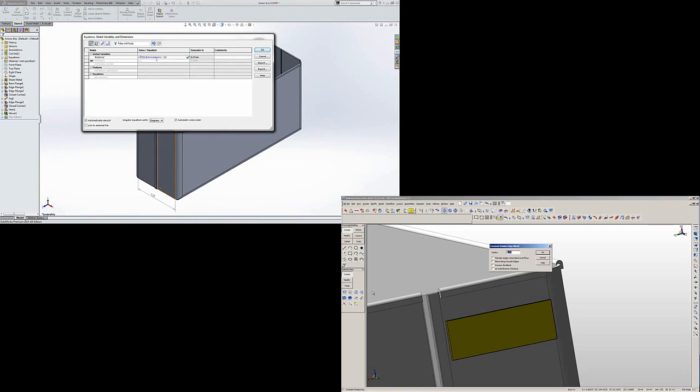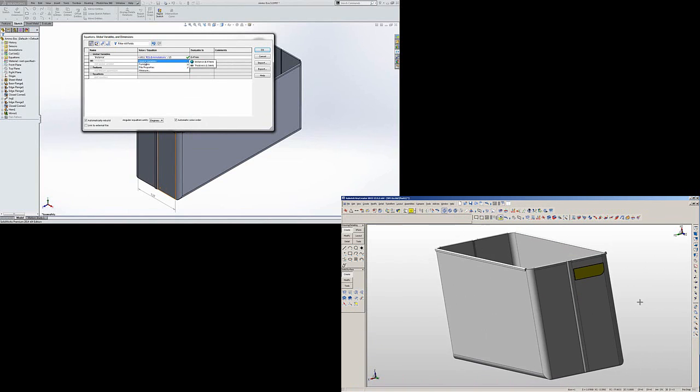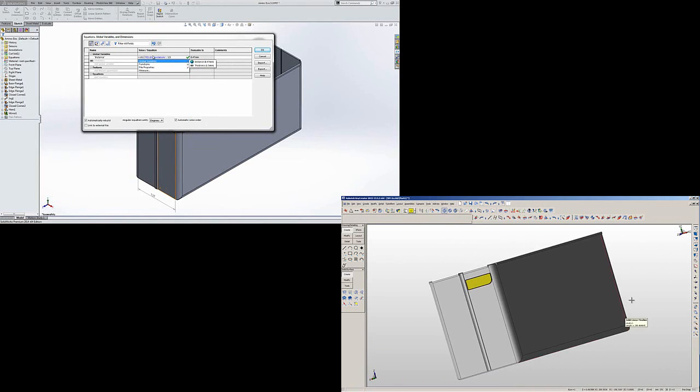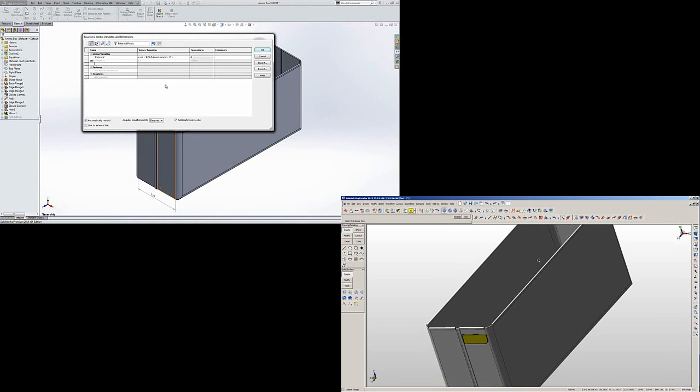So I'm going to go back into this equation, and I'm going to use a global function, and we'll go down to int. Now it's just a matter of deselecting that and going to the rear of the equation, tabbing across, and now it's actually automatically rounded that number down to a round number. I'm going to add another global variable, and this one's going to be instance odd.